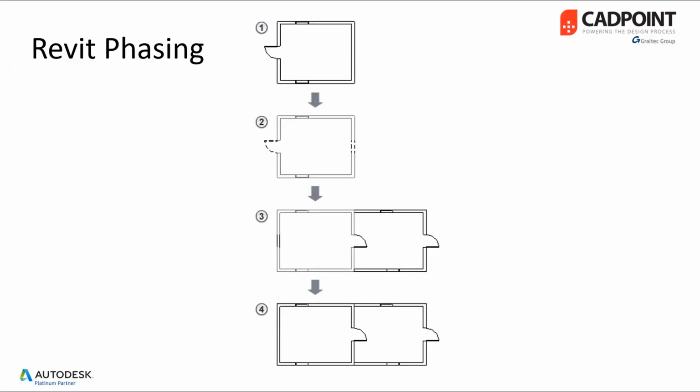You can apply phases to schedules. For example, in a large renovation project, a door schedule would usually list all doors created in the project. In a building with hundreds of doors, the schedule could become difficult to work with because the demolished doors would be listed with the post-renovation doors, instead of working with a schedule in which half of the doors are eventually demolished. You could create one pre-demolition schedule and one post-renovation schedule, applying the appropriate phase to each.